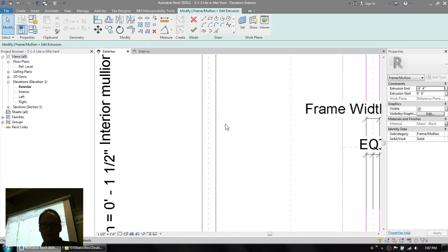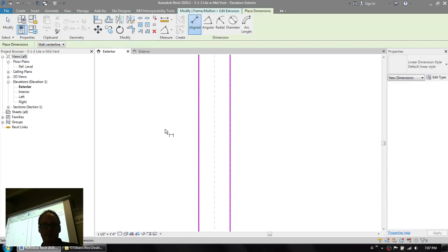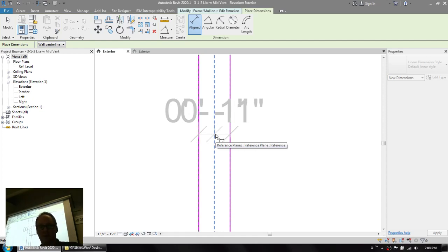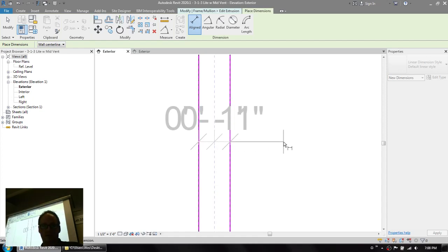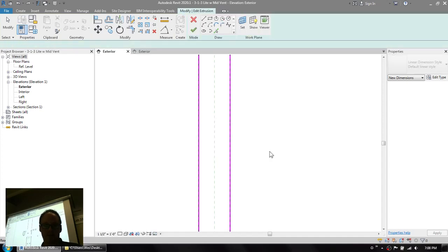So you've got your two pink sketch lines with a reference plane in the middle. So then we use the dimension command, and for the equality constraint we pick both sketch lines and also the reference plane in a single dimension. Click some white space and place it. Hold on, let me just do that again here. D-I.